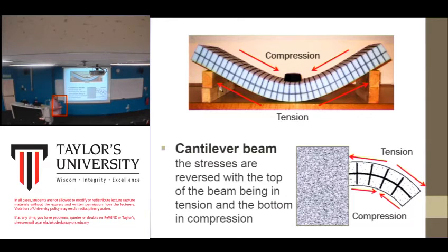But it is different with a cantilever beam. Which means if you put the sponge on a wall, on a surface, the top will be under tension, the below one will be under compression. Because the support we got only one, but this one got two supports. Okay.